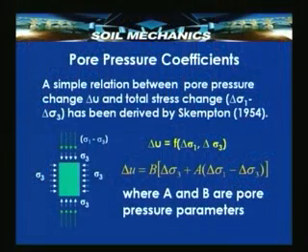simple, fundamental relationship. Skempton in 1954 derived a very fundamental relationship from basic considerations for evaluating the change in pore pressure during a triaxial test due to the application of the confining stress sigma 3 and then the deviatoric stress. The relationship is extremely simple. Delta U, the change in pore pressure, is simply a function of delta sigma 1 and delta sigma 3 which